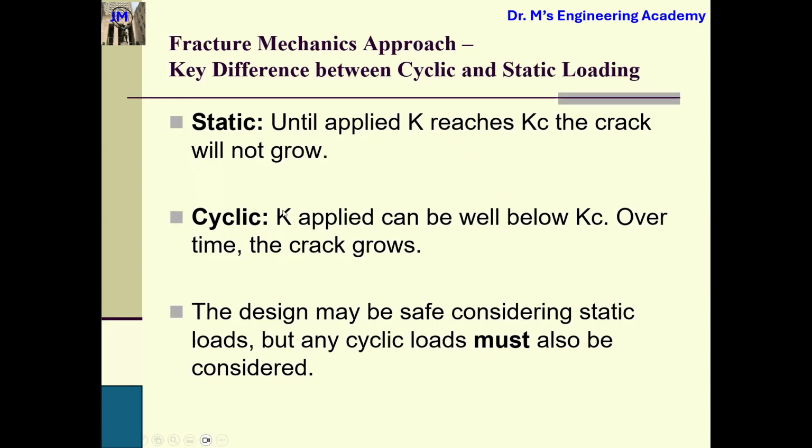Even though this K is very low, if we have cyclic loading, the number of cycles is involved. As time goes, even with a very low stress level, we still have a safety issue. Understand, guys? Because the number of cycles is involved, the time is involved.